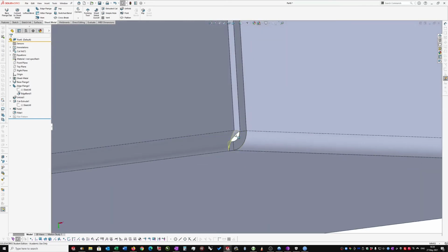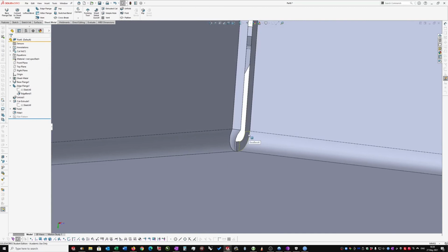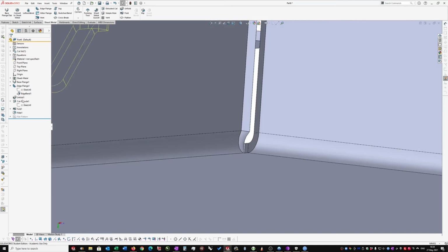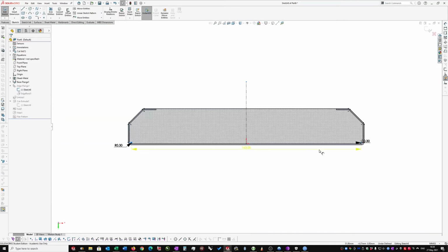Remember that went around there. So the problem is, anytime that you have a bend of some sort, the sketch itself has to account for the length of the bend, right? So the sketch doesn't account for the length of the bend, doesn't go beyond it. Let me draw it properly, and then you'll see what I'm talking about.